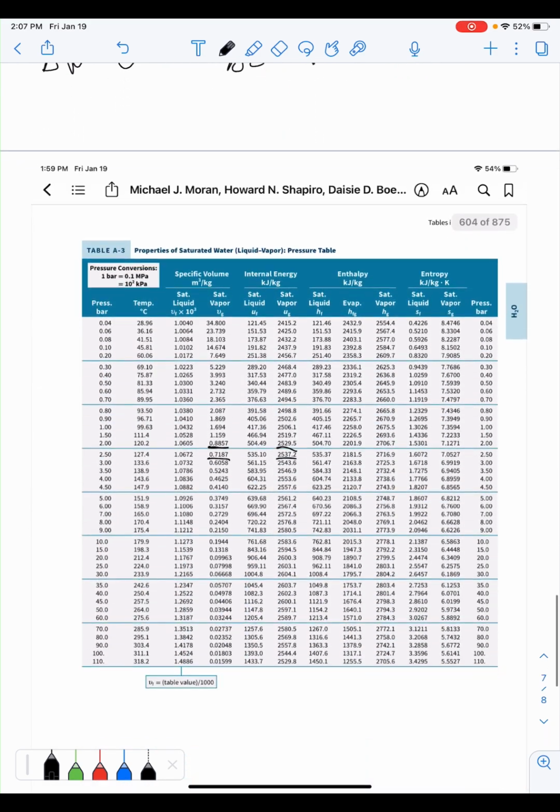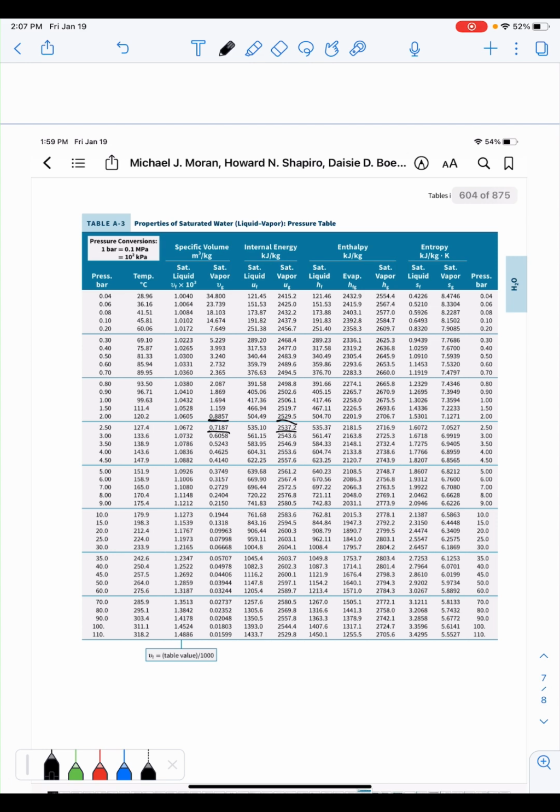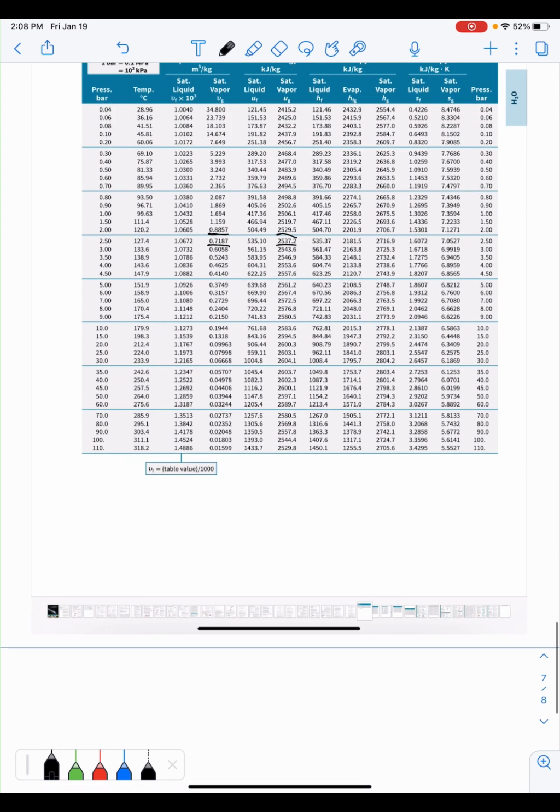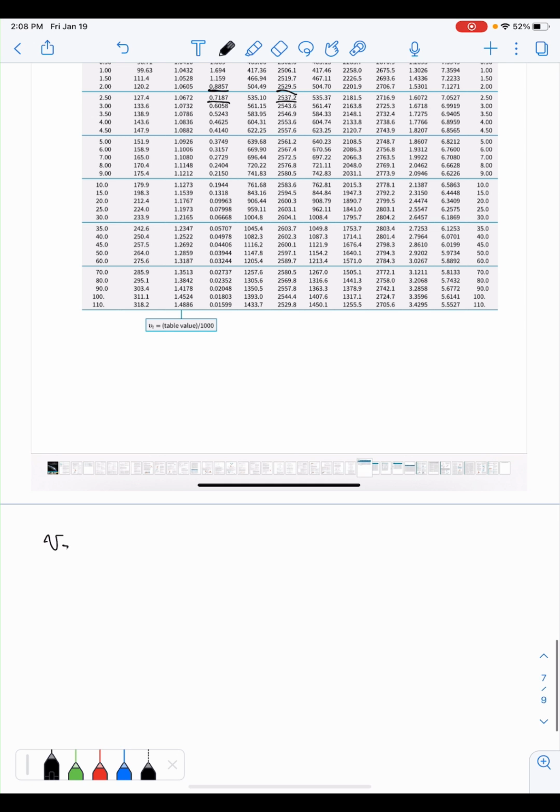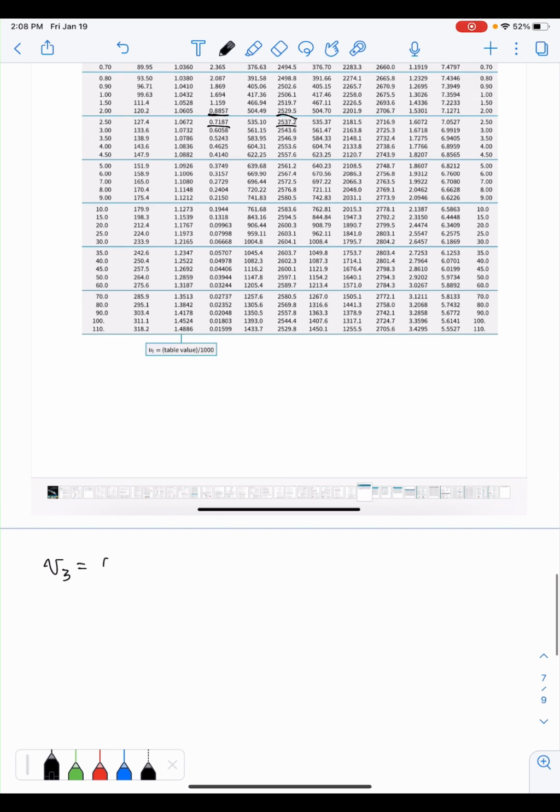Later on, either next week or in 2 weeks, you'll learn about steam tables. These steam tables are how you get the values you want based on your specific volume, pressure, temperature, and other variables. So we know that the specific volume we currently have, at state 3 and state 2 and state 1, will be 0.8475 cubic meters per kilogram.